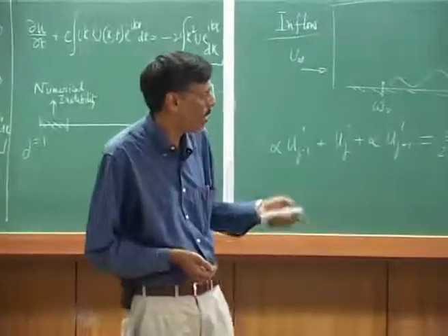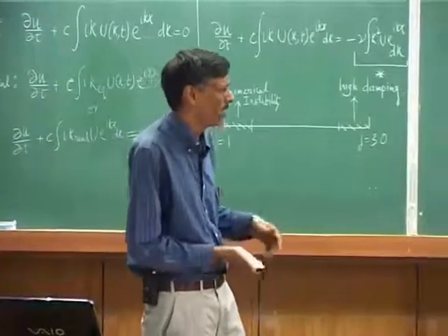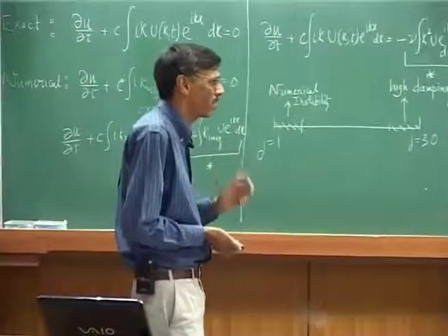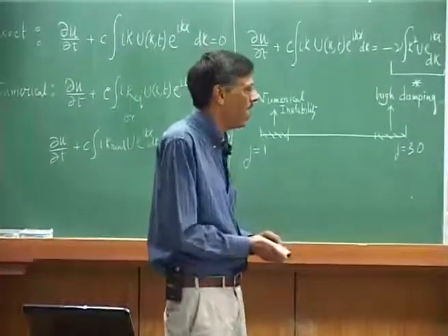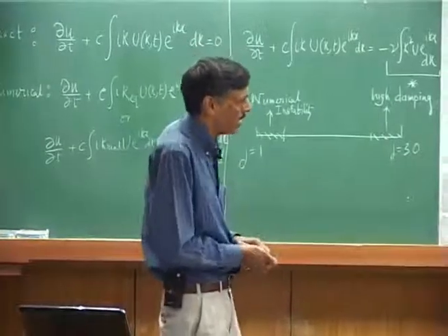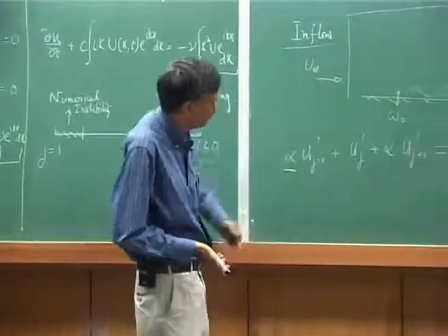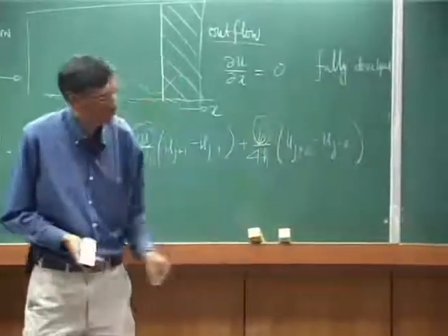Now, what you do actually is try to minimize the error created by this compact scheme with respect to a spectral method over the full range, and you can see that the departure is going to be a function of these three parameters alpha, a, and b.